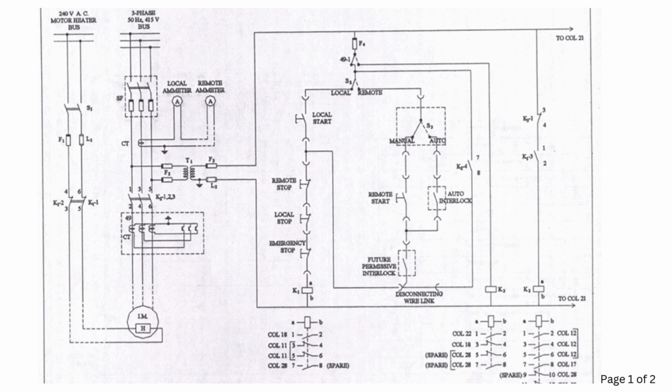Okay, so here you can see a local or remote selector switch, which allows the control of the motor either from the local site or from the remote switchgear location. This switch is positioned at the motor's local installation site. When the motor is undergoing maintenance or repair works, the selector switch is set to the local position so that it ensures that no one from the control room can operate the motor from the remote location.